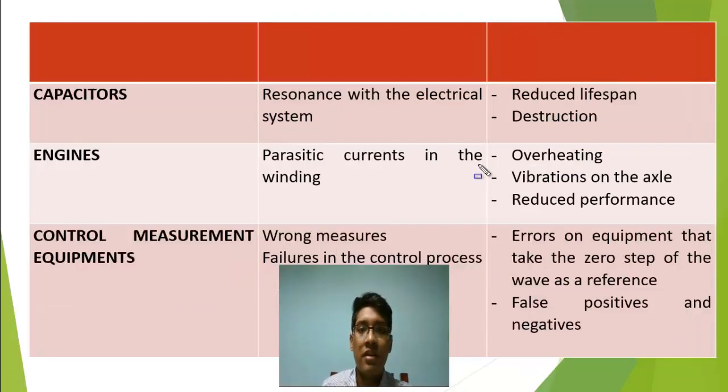On capacitors, the harmonic wave causes a resonance with the electric system, whose effect is an increase of the voltage in this element. Although the laminar dielectrics designed for capacitors allow high voltage, this produces a decrease of the service life and fatigue of the dielectric when overcharged for long periods of time, which reduces the lifespan and leads to the destruction of this electric